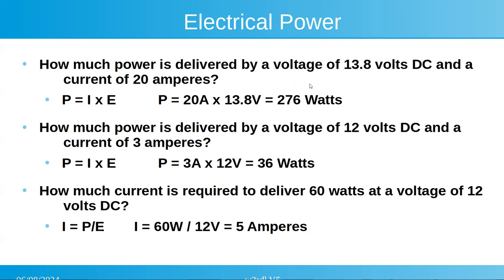Running at 13.8 volts, it's going to draw in the neighborhood of 20 amps if it's outputting 100 watts. But you're going to have 276 watts coming into it. So it's less than 50% efficient. You've got 276 to generate 100 on the end, hopefully at your antenna.